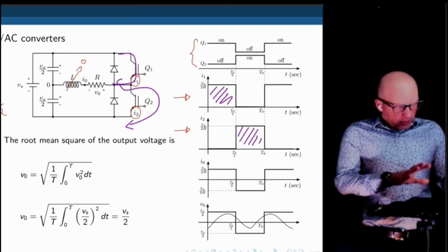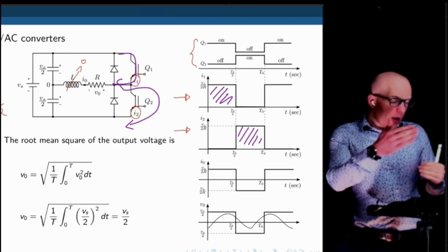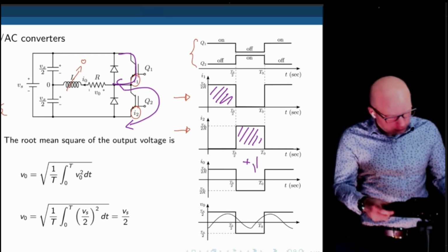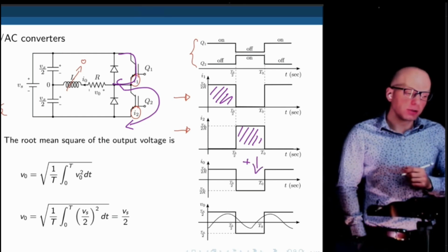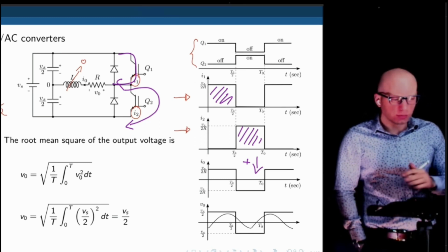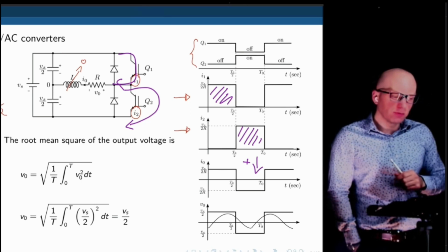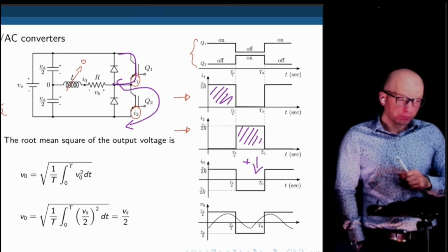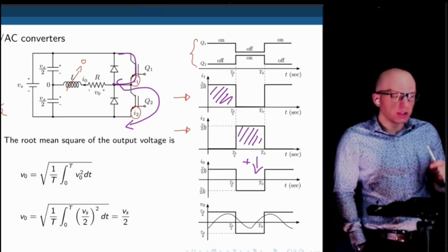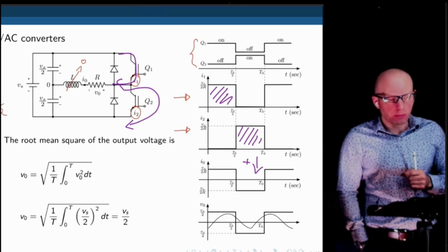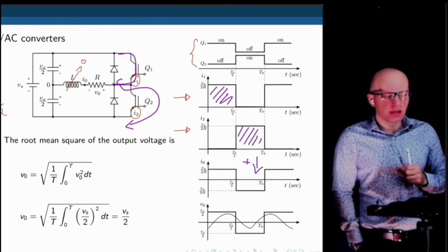If you plot them independently, that's what we see. If you now add them up, that's the actual effective current applied to the load, and that's the result. It's now a square waveform for a resistive load, and that square waveform will resemble this. See, the current now goes back and forth, and the inverter now creates an AC voltage.